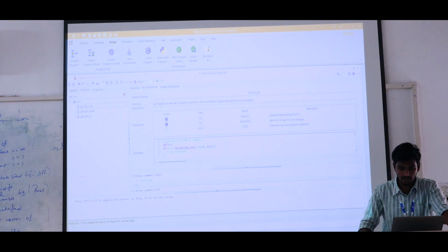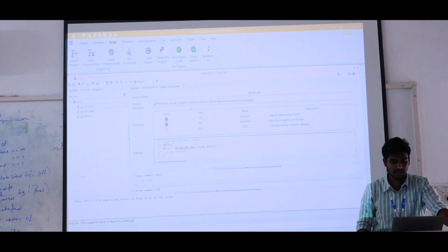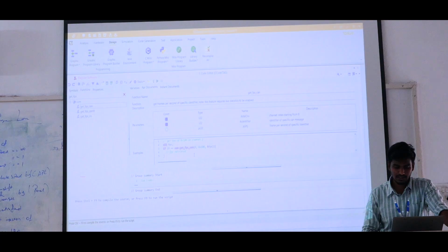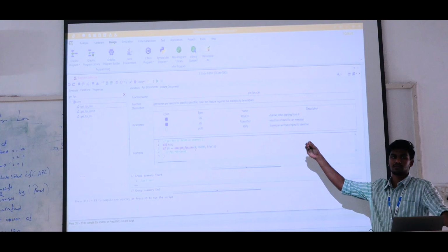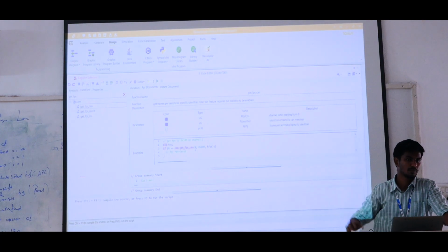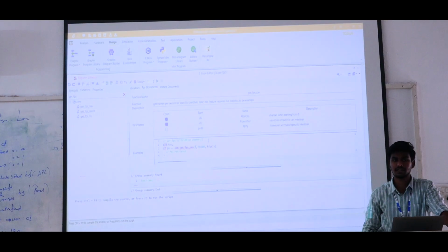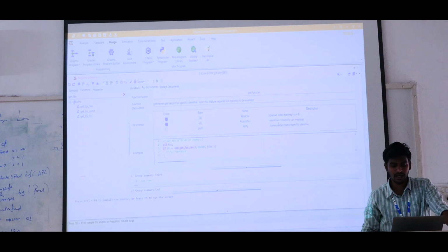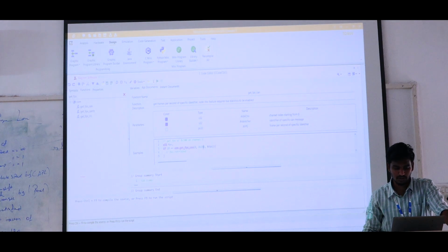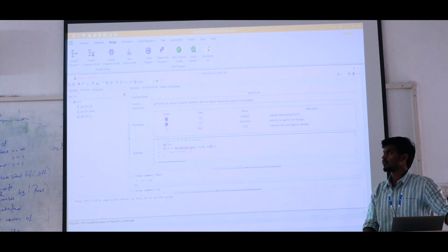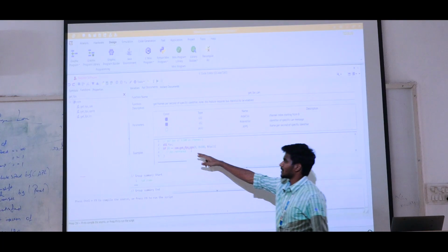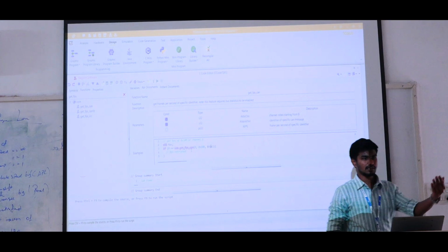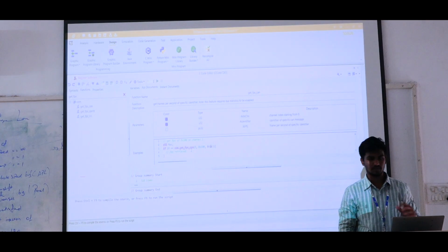This function is used to get the frames per second on a specific identifier. Using this function, the first parameter is the channel index, where the message is going to transmit, channel 1 or channel 2 like that. If you are working with the first channel, the channel number is 0. So the index value for the second channel is 1. Then which ID do you want to get the FPS for? ID number 123 and FPS. Wherever we use get, we definitely need to use the log. Log means it will print whatever values it is gathering in our log statement. Okay.